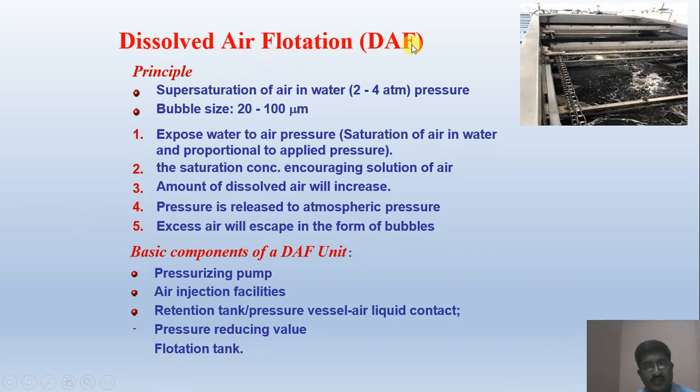Dissolved air flotation, or DAF. This is a type of flotation where air is the important factor. The principle is the supersaturation of air in the water, at 2 to 4 atmospheric pressure. Bubble size is 20 to 200 micrometers.